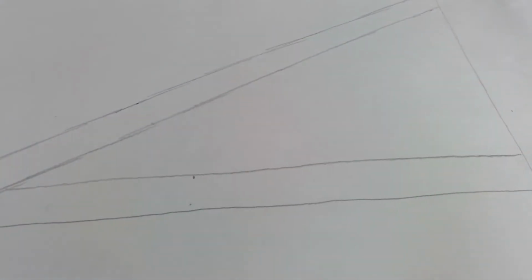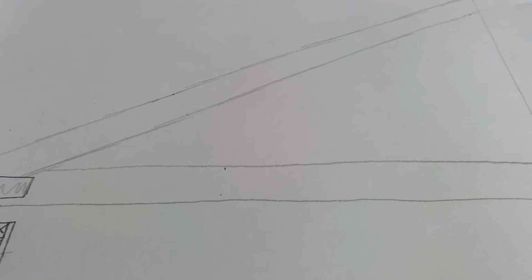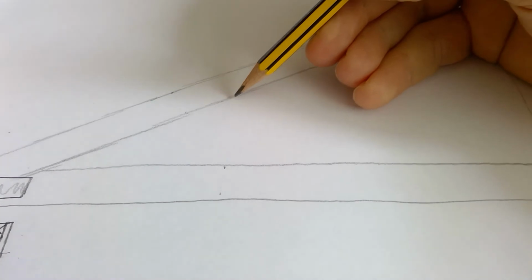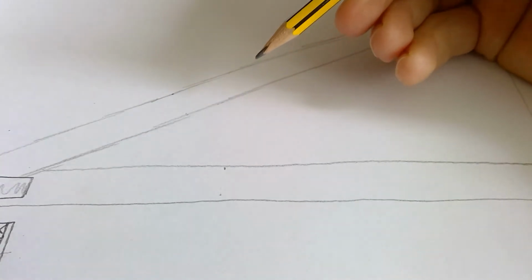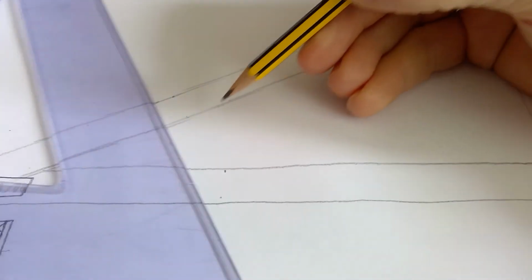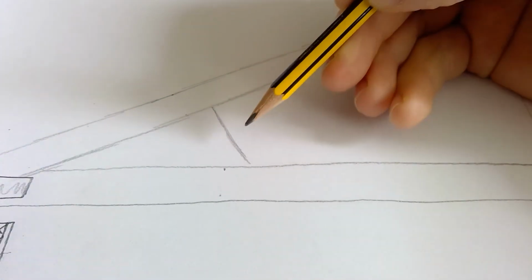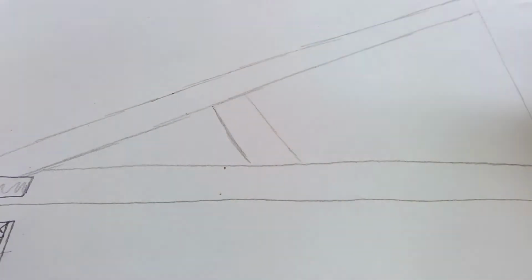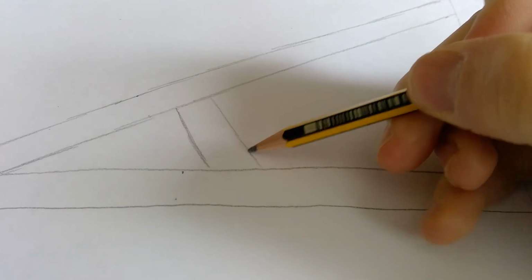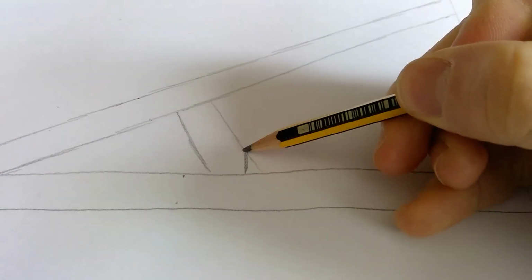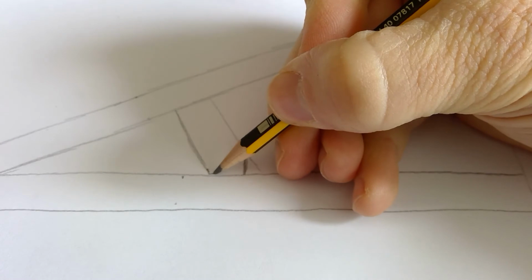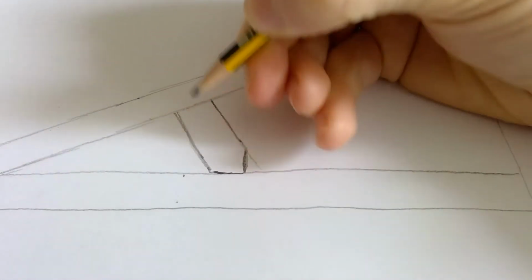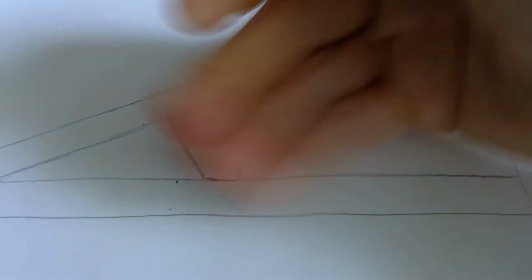Now when it comes to drawing those structural members of the roof, we're going to go for a fink truss. It's the most common one. Look, you don't need to overthink it. Just come up maybe even enough space up here. Get your 60-degree set square, and draw a 60-degree angle roughly like that. Go across 150. Do your next piece. Okay, this needs to go up to the center also. Generally speaking, this piece, you know, pick a point and have that drawn like that. Again, don't overthink sizes of that. Just get that shape. That's the way they're cut.